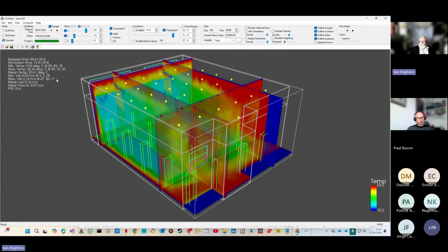Because we've eliminated pressure, our boundary condition calculation is a lot more complicated. So we can't just put face velocities in. We have to calculate another variable, which is what gives us the elimination of pressure and the robustness and stability.